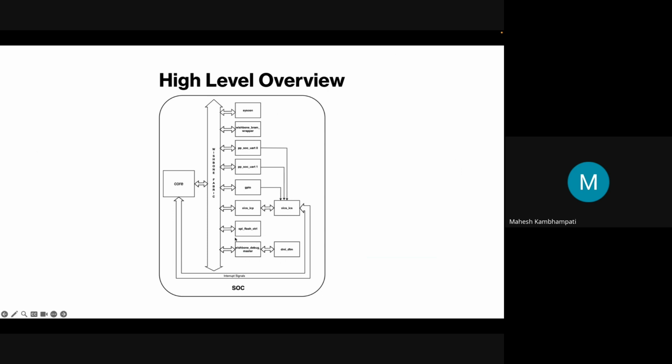And there is the flash memory. It usually stores things like BIOS and the Linux image. Sometimes, if our SoC doesn't have a DRAM specifically, it also stores the main program. So when the boot code loads up, the main program from the SPI would be loaded onto the BRAM, and the main program starts executing from the BRAM.